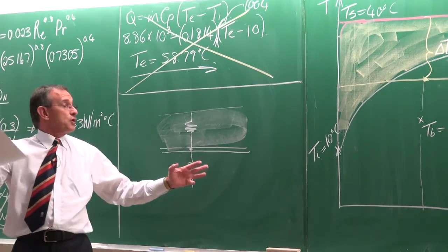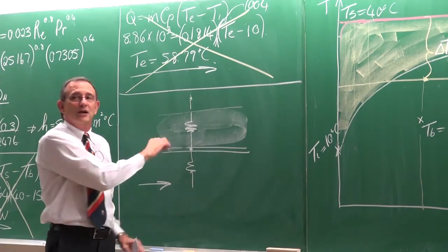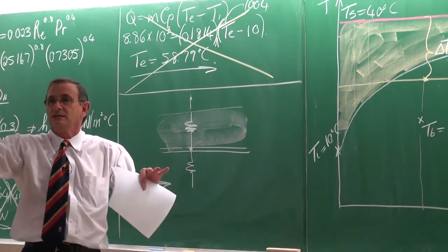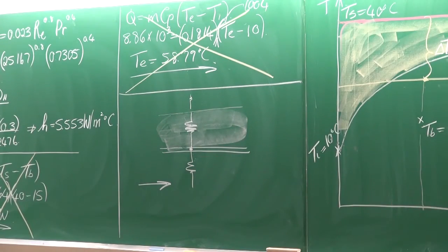But what you're also supposed to do now with insulation material is also look at the heat transfer to the environment. Again, you have to put that resistance term up there also and take it into consideration. So that is actually the correct way, and we're on our way to doing that.